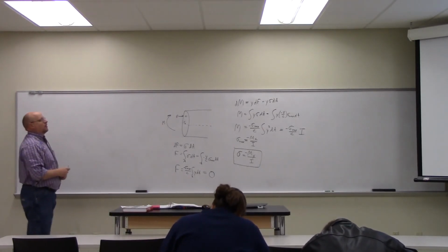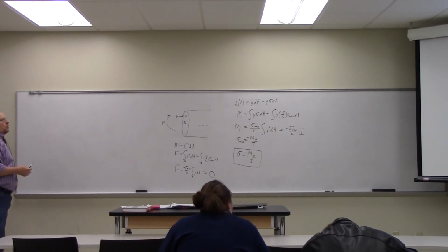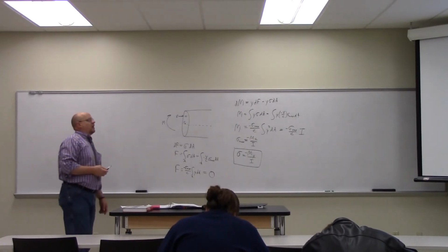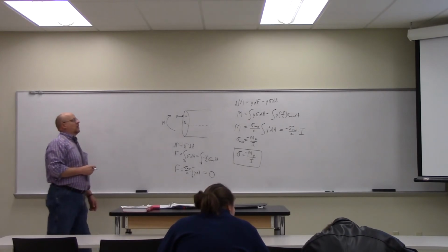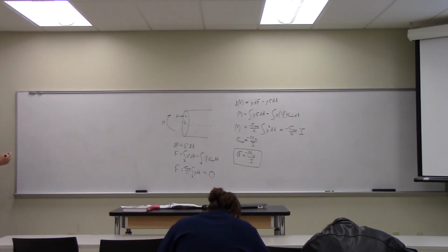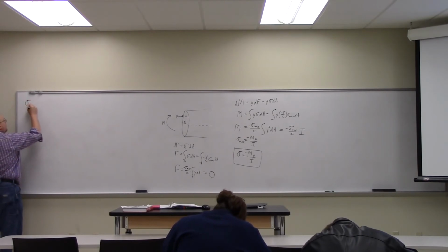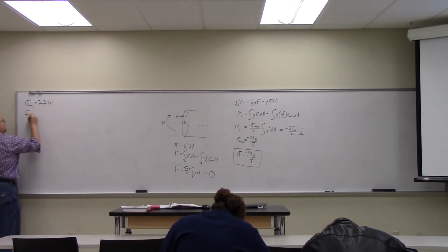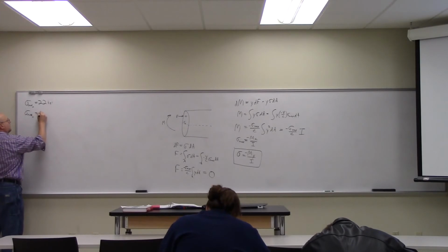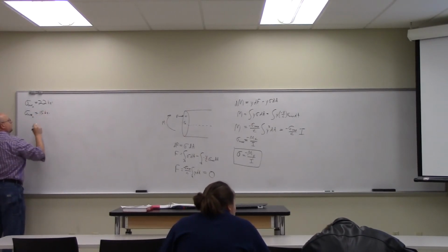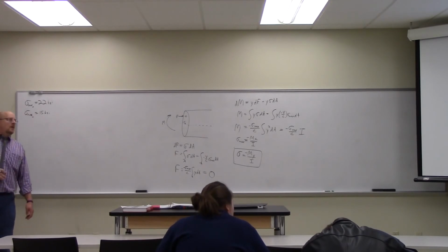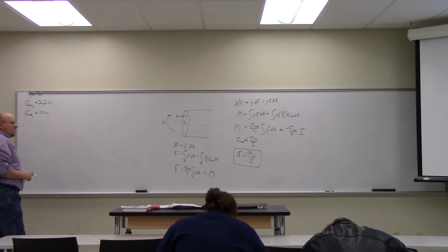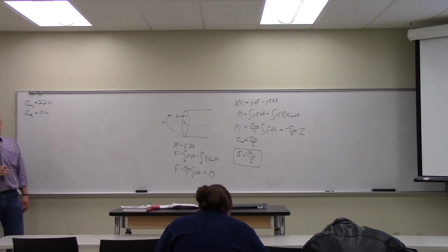All right, remember, as the triangular cross-section shown, determine the largest internal moment that can be applied to the cross-section without exceeding the allowable tensile and compressive stresses of 22 and 15 KSI respectively. So sigma max in tension is 22 KSI, and sigma max in compression is 15 KSI. And we want to find out how much of a moment this triangular beam can support.